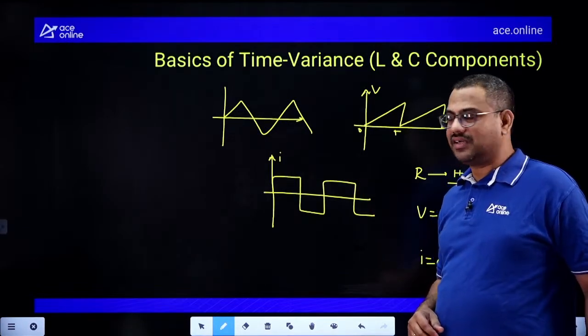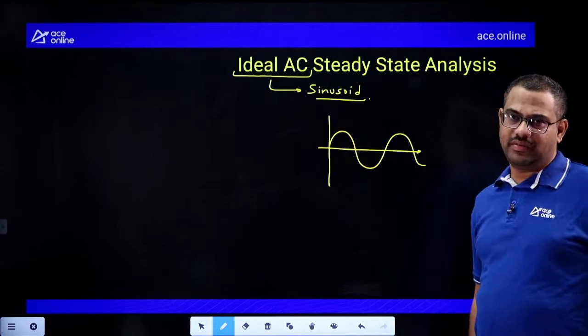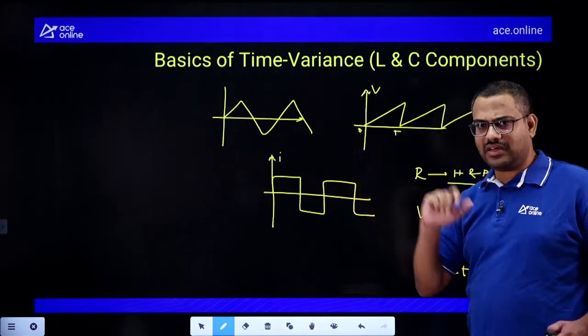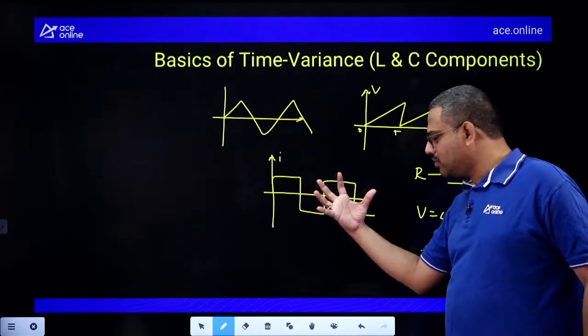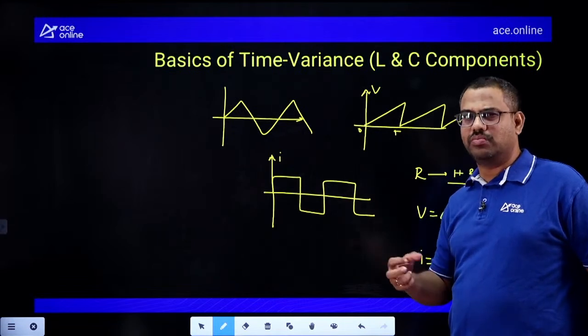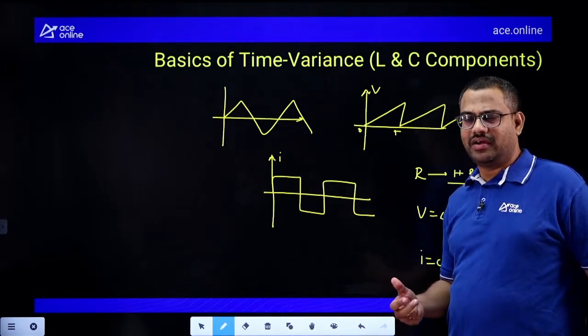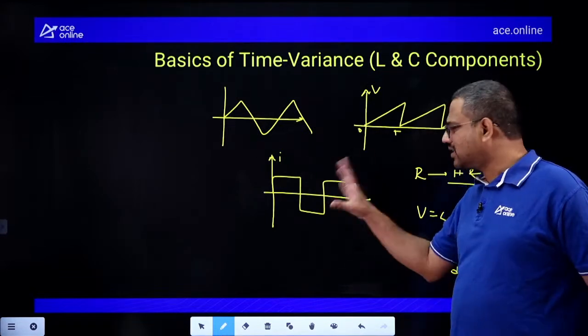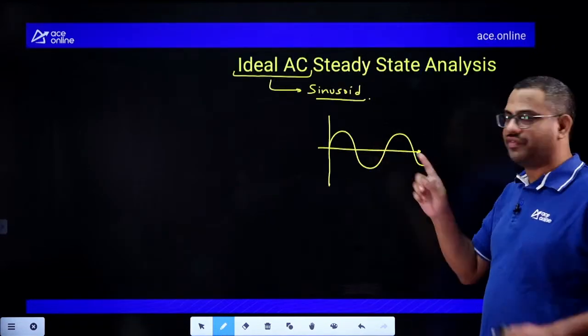So that is why, sir, only the AC waveform is number one. If you give this, best performance will come. If you give the other, yes, it may work, no doubt. Our induction motor of a fan will run with it. But pulsating torque, harmonics, more losses, excess heat, all these are the disadvantages. That means in terms of utilization and conversion, it is the worst waveform at power level, versus the best waveform at power level.